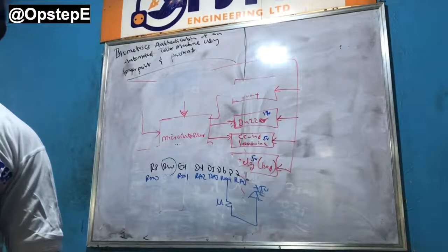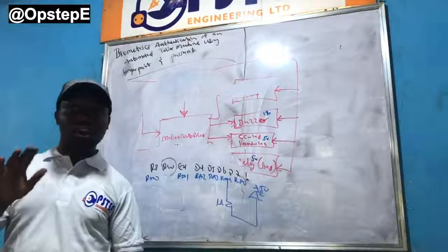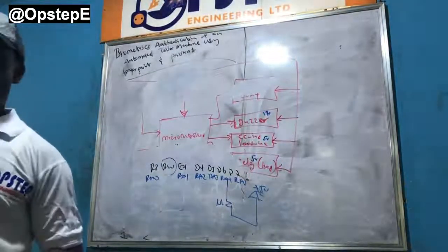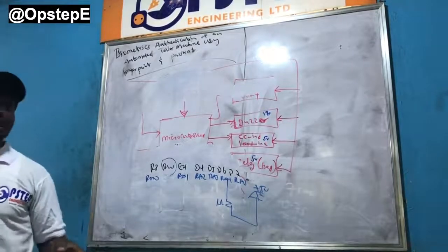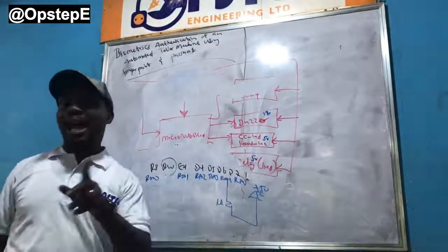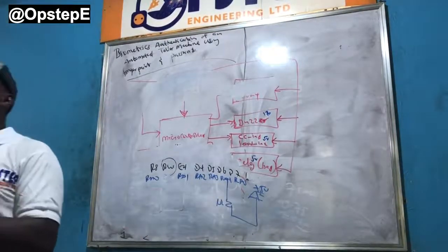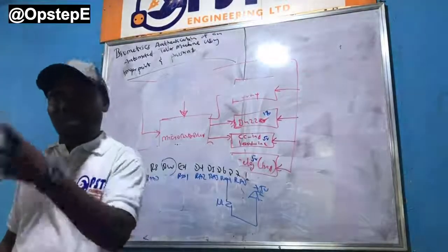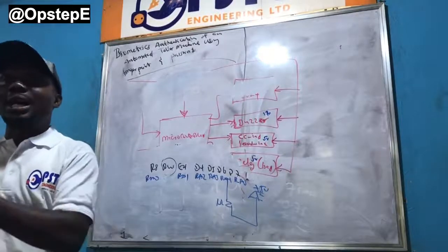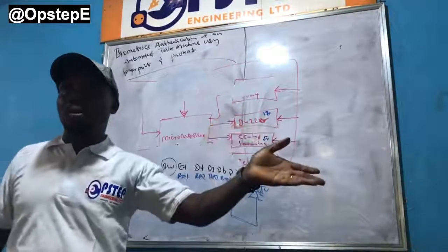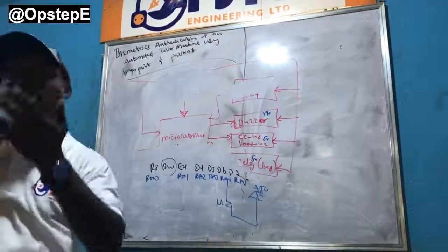Since you say it's regularly an input pin. No, it's an input output pin, but it's best used as an input pin. More importantly, it's also the same pin that has your timer clock in. Are you with me? When you need to design a counter, you need to count events. That's the pin you use, because it's attached to your timer, so you can count events and increment the timer, using the timer as a counter within the microcontroller.